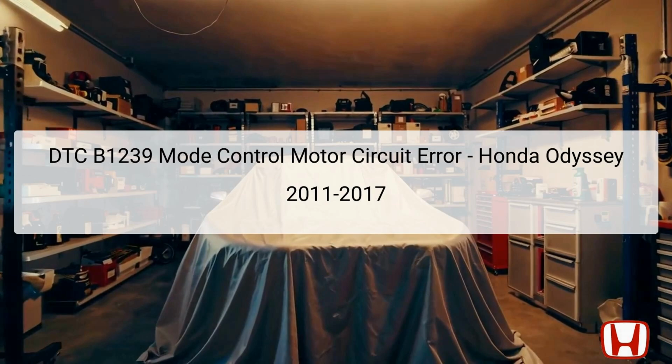The Diagnostic Trouble Code DTC B1239 for the Honda Odyssey models from 2011 to 2017 indicates an issue with the mode control motor circuit. This error can signify either an open or short circuit within the front mode control motor's wiring system. The mode control motor is essential for regulating airflow operations through different vents within the vehicle's climate control system. This component directly affects passenger comfort by directing air from the dashboard, floor, or defrost vents.